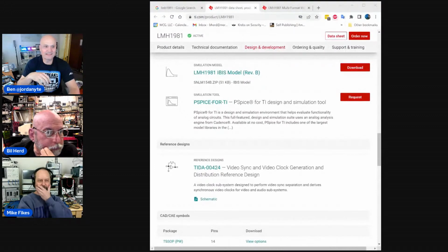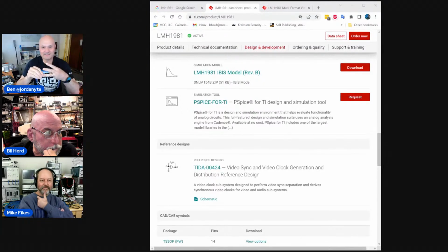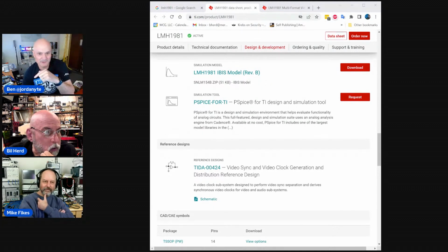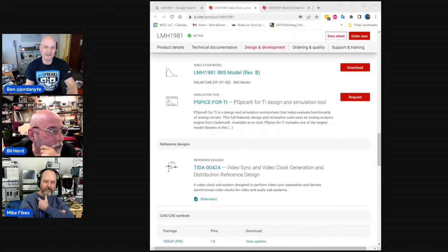So I ended up with 3 versions of Model Sim on my computer because I had the Xilinx Starter Edition, the Altera Starter Edition, and the Lattice Starter Edition. And depending on what part I was targeting when I ran a VHDL simulation, I'd have to specify which path to Model Sim it had to use to launch the executable, or it wouldn't work. It would throw up saying, "Oh, you don't have a license for these other libraries."